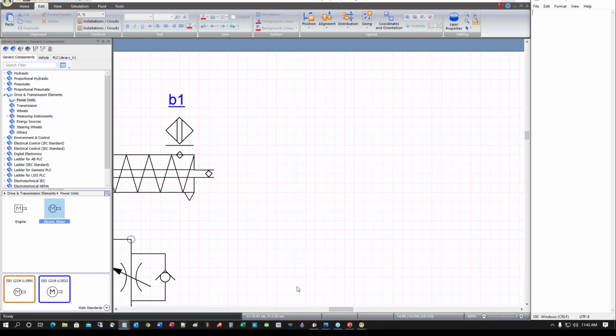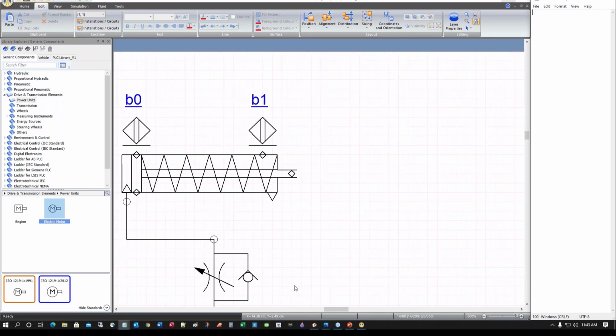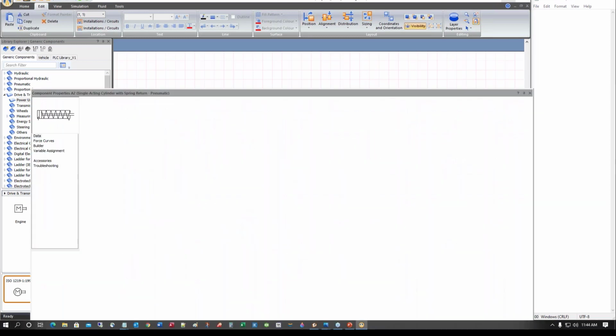So first thing in the animation, I have to define exactly what I want to do. So basically, I want to move a box. I have a box here that we're going to drop. And then when it's going to be at the level of this piston, I'm going to have the piston in the sequence. You're going to start pushing this box toward the end of stroke of this pneumatic cylinder. So basically, I'm going to start pushing the box when this cylinder is at 20%. So first of all, let's say at 20%, where?